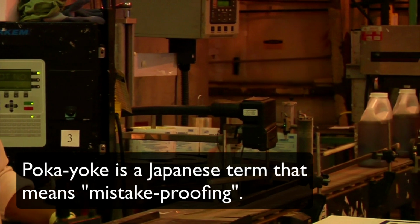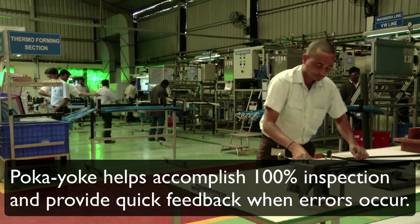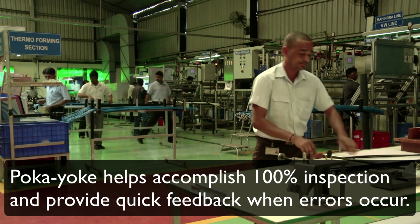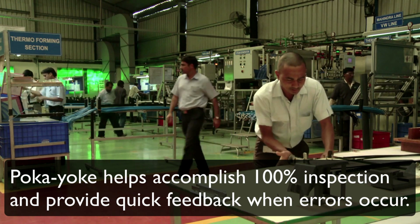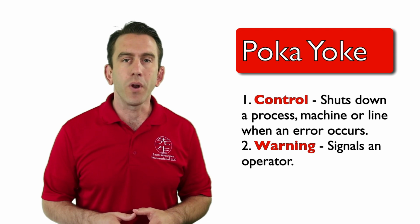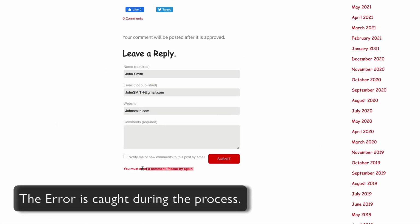Poka-yoke devices essentially help facilitate 2 very critical aspects in preventing errors. They help accomplish 100% inspection. They also provide quick and almost immediate feedback when errors do occur that helps an operator take corrective action before the error turns into a defect. In the simplest form, a poka-yoke will either shut down a process, machine, or line when an error occurs, or signal the operator. The most effective poka-yokes are achieved with source inspection.